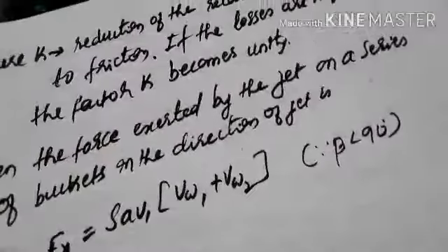Then as it comes to this position, it will release the water it holds. If we are not giving any provision to release the water in a proper way, then this will fall on the back of the bucket, which will reduce the speed of the runner. So that's why the deflection angle is given as 160 to 170 degree. Then this angle will be generally 10 degree or 5 degree or 15 degree.